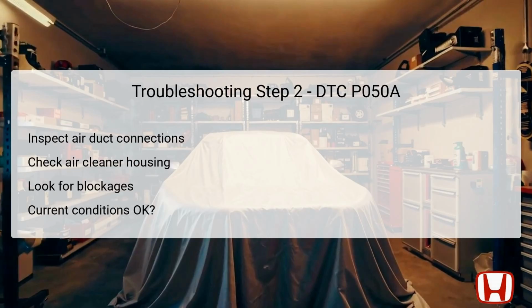In this step, you should perform a thorough inspection of the intake air duct connections and the air cleaner housing. Checking the air duct is vital, as blockages here can lead to insufficient airflow problems, which directly impacts engine performance. Using visual inspections, technicians should look for any signs of kinks, obstructions, or loose connections in the duct. The air cleaner housing should also be visually examined to ensure that it is free from dirt, debris, and damage, as any contamination could impede airflow.